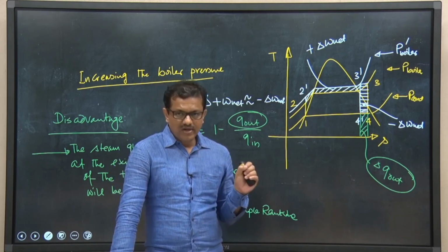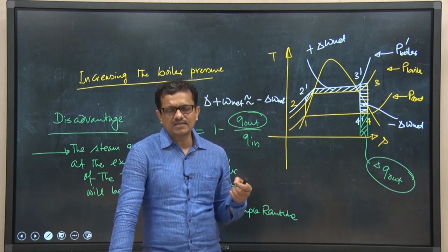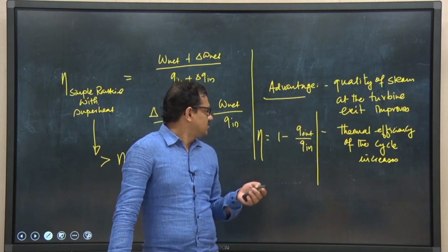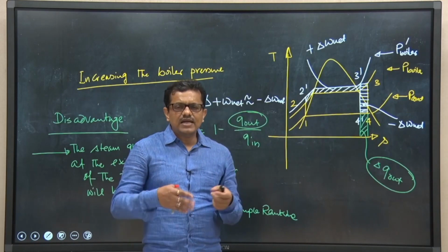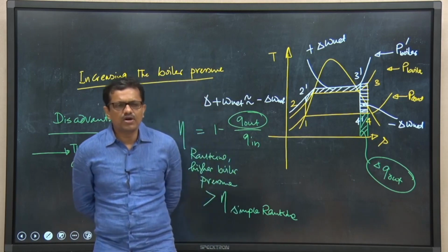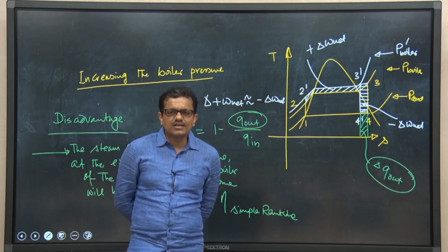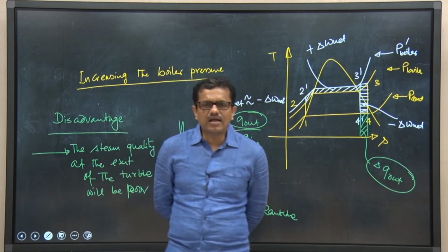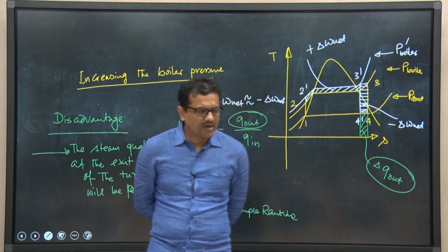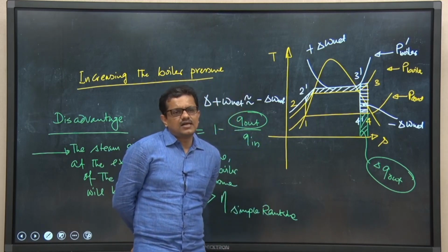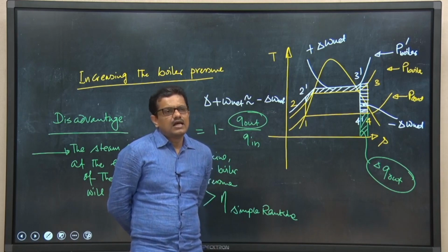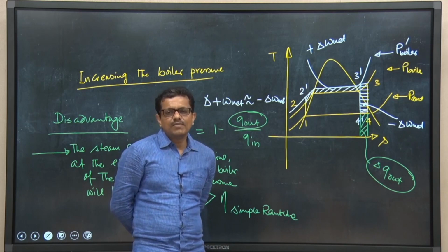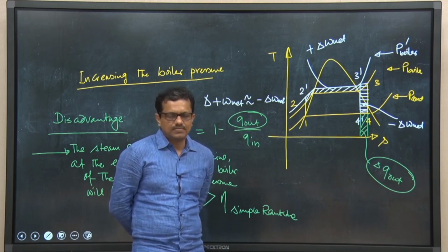Today, whatever we have discussed, regarding superheating the steam, the only disadvantage is that we need additional cost for the installation of a special system for superheating as well as the operational cost. Also, we should be careful about the selection of the turbine blade material, such that it would be able to withstand that high temperature.